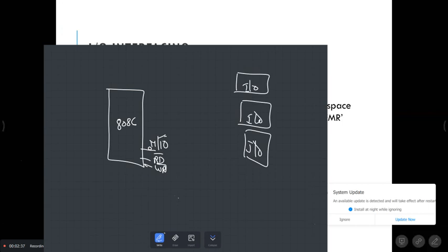If this particular signal is 1, then the microprocessor is doing read and write operations to memory. Hope you are understanding this. You have memory connected to this microprocessor, and I/O also connected to the microprocessor. Now, how do you differentiate reading and writing to memory and I/O? If you give 1 to this pin, it does read and write through memory. If you give 0, it does read and write to I/O devices. That is the difference.